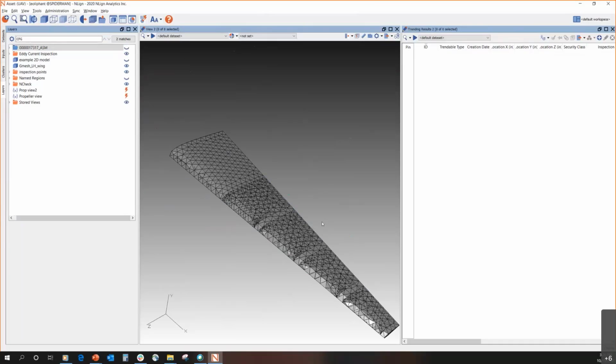As an example, in manufacturing, we found we were getting a lot of defects in a certain area, and we loaded in some of the tooling information, and we saw that those defects correlated with a feature on the tool. We went out and looked at that specific tool that a lot of the parts were coming off of with defects, and we found that there was some issues with that feature. So we had it serviced, and the defects went away. It saved us a lot of heartache and grief by figuring that out, by loading in some of the different models that were associated with our parts.